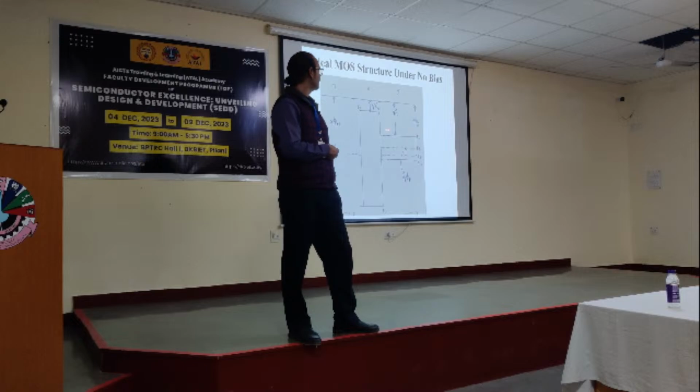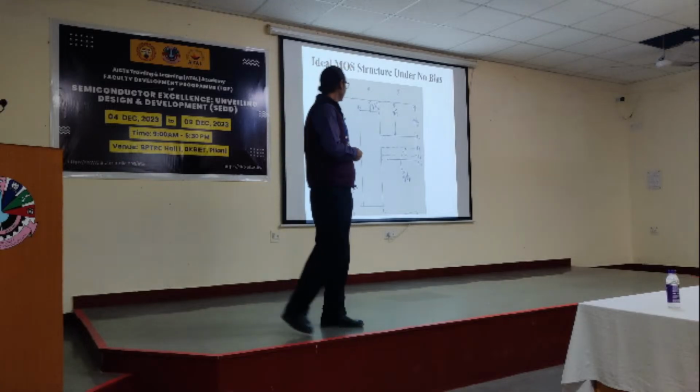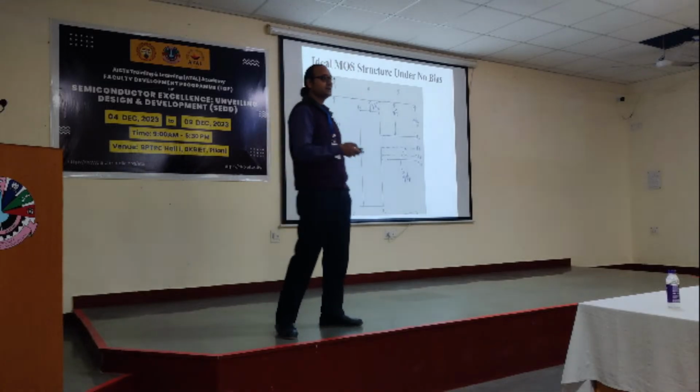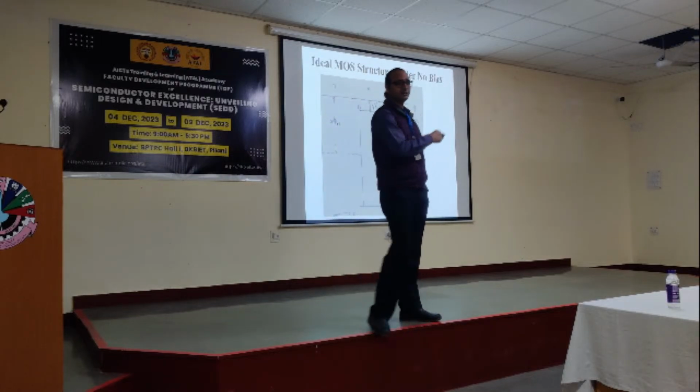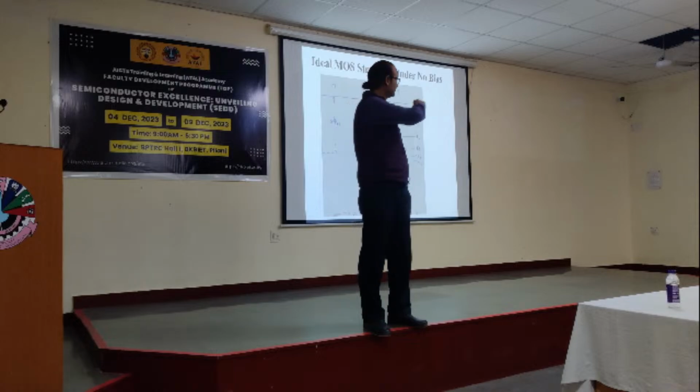So the voltage reduction for flat band will be Q in the oxide divided by the capacitance of this oxide. So what is the net flat band voltage then? Phi ms minus...